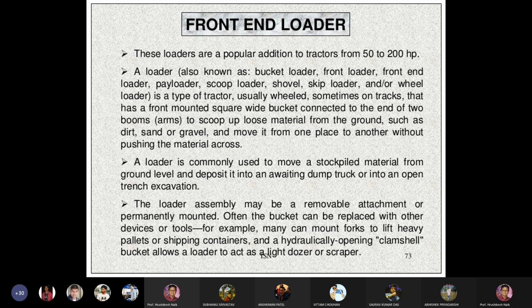So after drilling and blasting, the material is to be loaded. The loading operation is carried out by the shovels. The shovels are of different types. Electric rope shovels are there, hydraulic shovels are there, backhoes are there. So these are the loading machines. The dragline can be used for the overcasting purpose. So the dragline is not a loading machine. It is an overcasting machine. So drilling, blasting, and loading is done by the shovels.